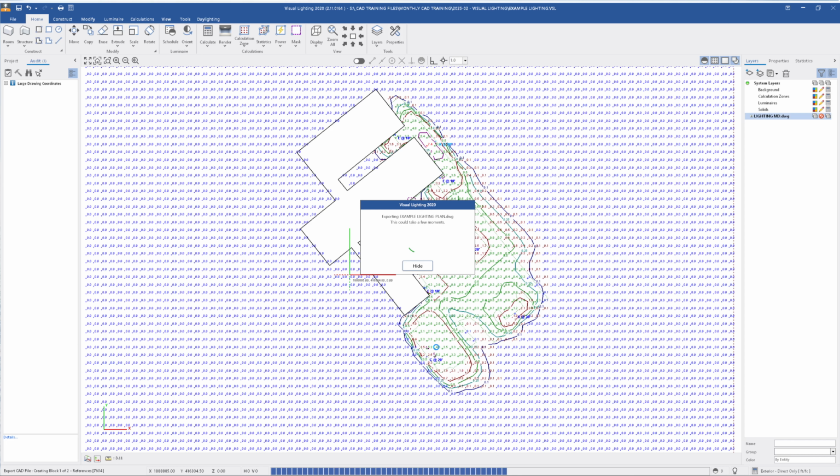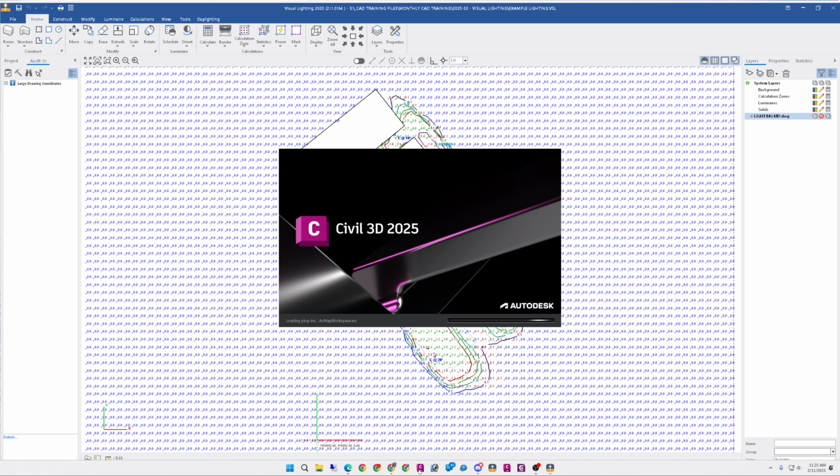And what I have found is it's best to work on this drawing separate and do not import it into your plot sheets right away. You want to work on it separate, get it ready, and then you can copy and paste it into your plot sheets. If you try to do it in your plot sheets, it can really bog it down because there's a lot of extra crud that's brought in with this process. And again, we end up having to clean this drawing up that we're going to do now.